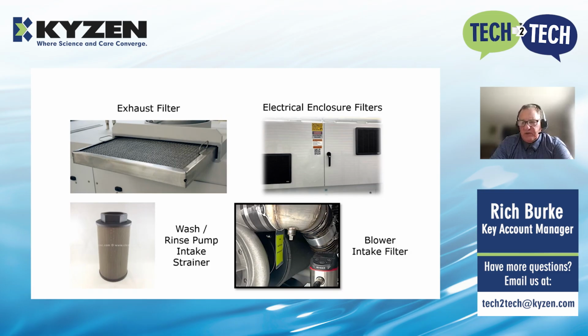So, for example, we might have a filter in our exhaust system. And if that filter were to become clogged, or as it becomes clogged, I should say, it creates a challenge for the exhaust system or ventilation system to pull enough exhaust within the machine, and eventually it can lead to steam escaping from our cleaning system itself. So that's very important to make sure we're maintaining our exhaust filters.